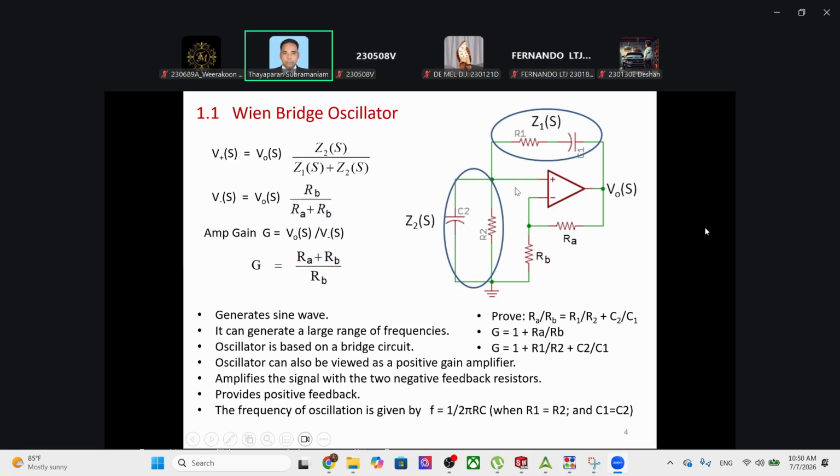You have to check component by component first. Do not simply go and connect all the circuits on the breadboard and observe the output. That's how you progress step by step. Otherwise, if you connect everything on the breadboard and the output is not as per expectation, then you will have huge debugging time.